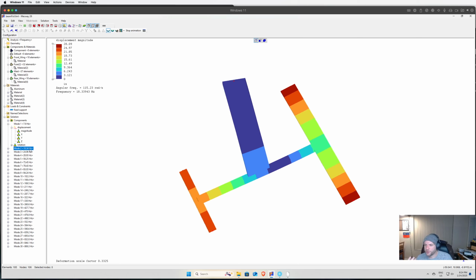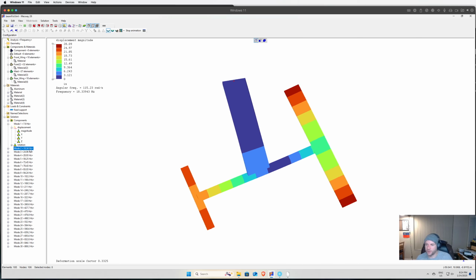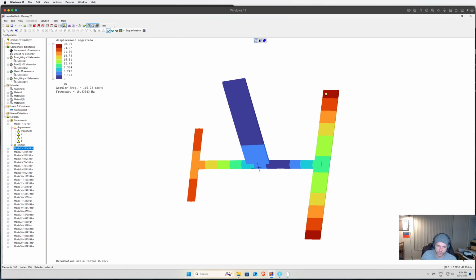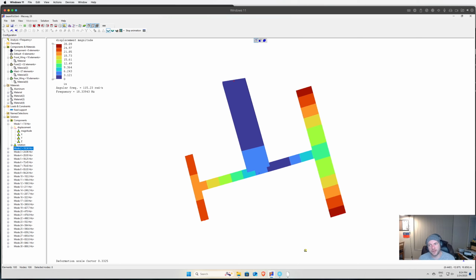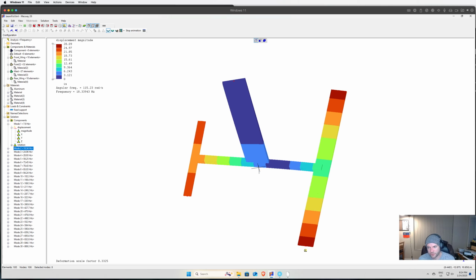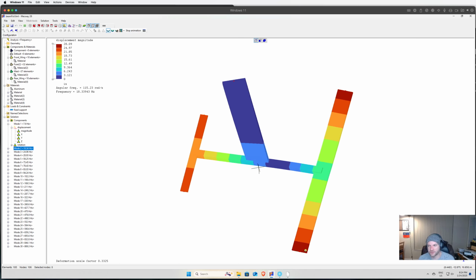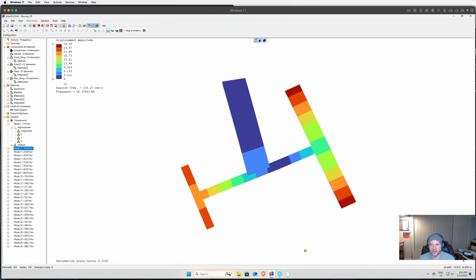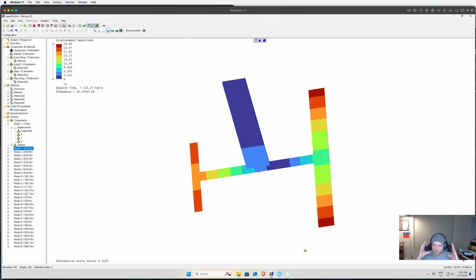But this kind of shows you why mass is so important on these things, especially at the wingtips, because you get all this moment of inertia out at the wingtips. And I had to calculate the moment of inertia of these shapes. And they're simple shapes. That's why I kept them simple, just for this demonstration, trying to understand what's going on, which I think is always a good way to start analyzing a problem: just simplify everything to try to understand fundamentally what's going on.